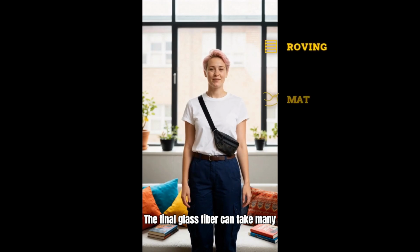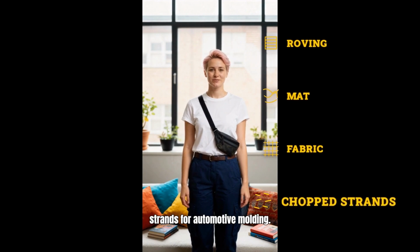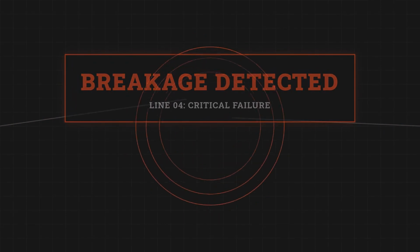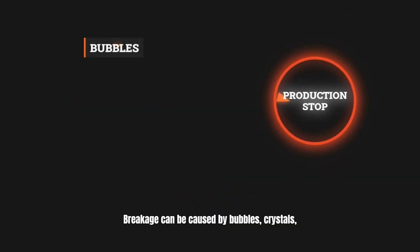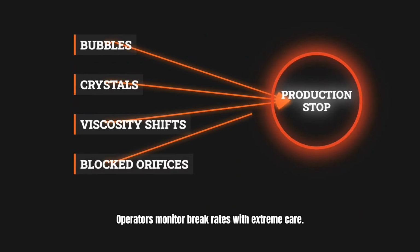The final glass fiber can take many forms, from woven fabrics for aerospace to chopped strands for automotive molding. One of the biggest plant challenges is fiber breakage. A single unmelted grain or bubble can stop production. Breakage can be caused by bubbles, crystals, or even air turbulence. Operators monitor break rates with extreme care.